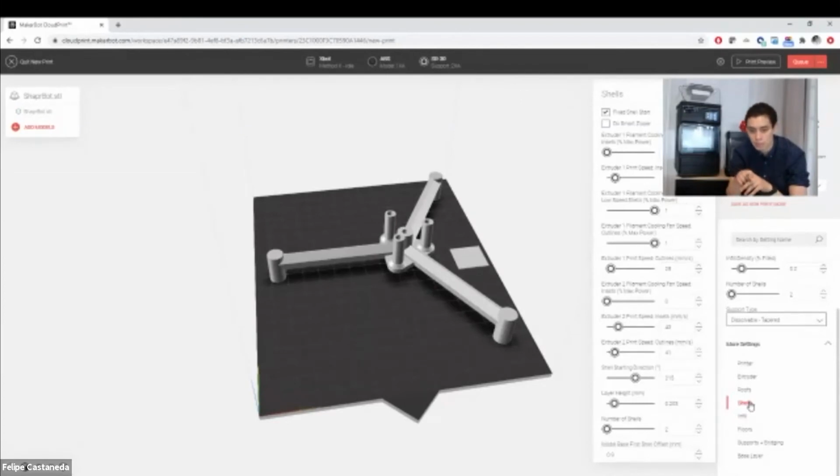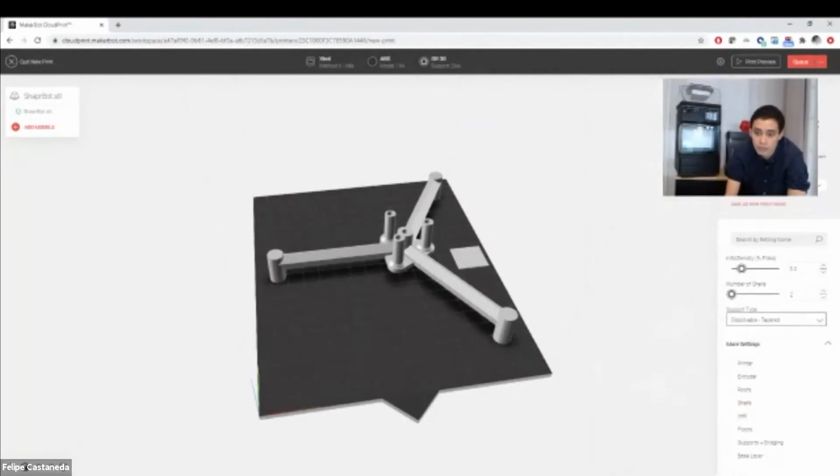Now, I would recommend, especially if you guys are just getting started with the printer, to stay within the defaults. Those have been thoroughly tested by our engineering teams and essentially work really well with the Method and with the material combinations that we offer. And once you've selected either one, balanced is going to give you a nice in between with about 20% infill, a straightforward printing process, a pretty good balance between the time that it will take for your part to be printed out and the actual sturdiness of the part.